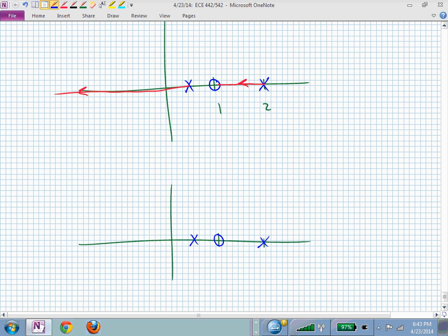I can cancel if things are inside the unit circle, can't I? I just can't cancel poles or zeros that are on the unit circle or outside the unit circle. So I can't cancel that 0 at 1, and I can't cancel that pole at 2. I better not be sprinkling poles and zeros to cancel poles and zeros outside the unit circle or on the perimeter. But that doesn't mean I can't introduce unstable poles and or zeros.